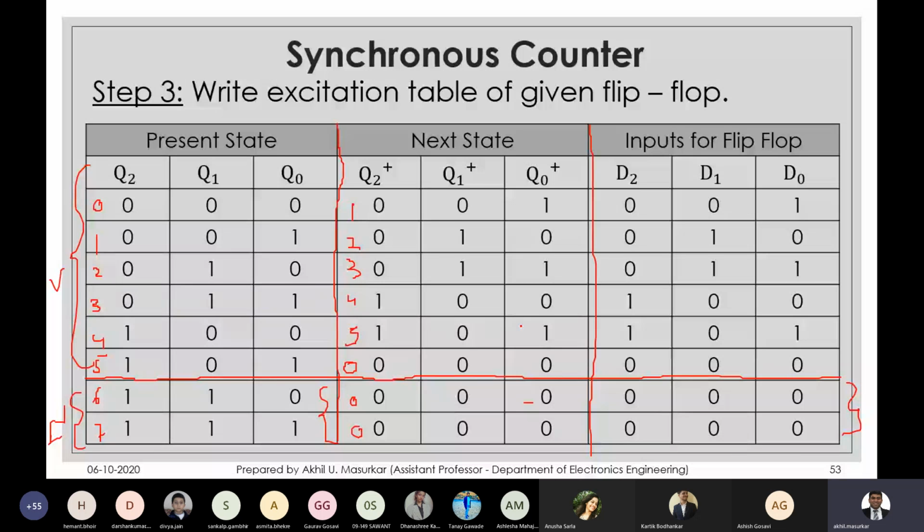When the number of ones reduces, the possibility of getting a quad or an octet reduces and we get isolated cells or pairs. So when the reduction is less, we will get more hardware. That is at the expense of additional hardware.